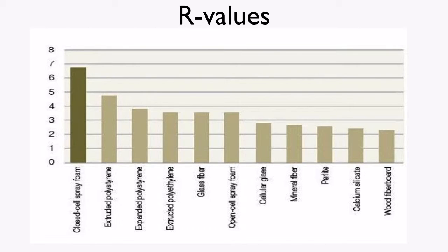So which insulation you choose really will often, or should, depend upon factors other than the R per inch, because there's a lot of hype around new products or new iterations of products. Again, whether we're talking about fibrous products or foam or bats, they have very, very comparable R values per inch.